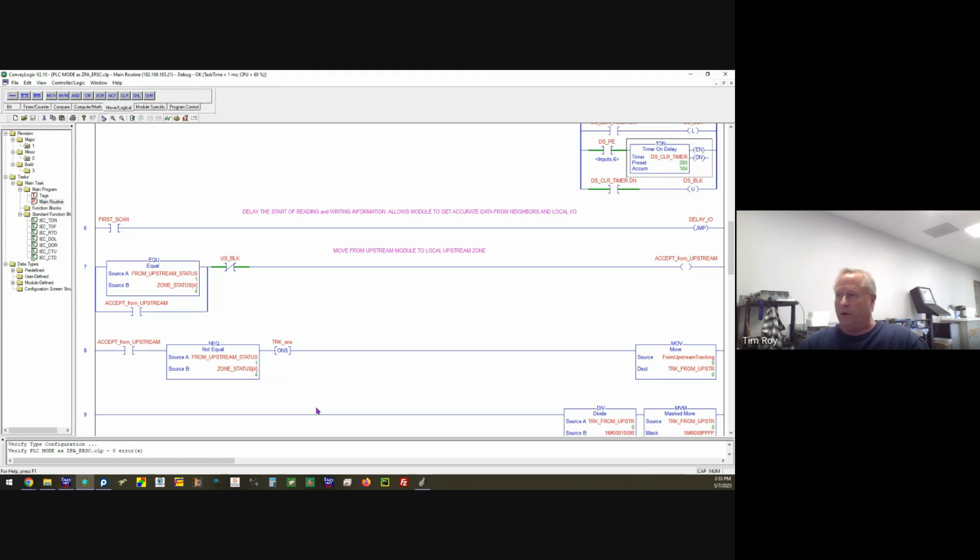Once you have your program and once it is downloaded, the thing you would want to do is look up here at the top, this last part. Task time, less than a millisecond. That's equal to Allen Bradley's scan rate. So the scan rate of this program running internally on the card is less than a millisecond. Okay. So this is actually running pretty good internally.